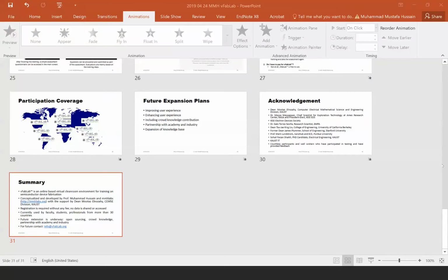So let's say that when we are done with the module level, then we will be providing the opportunity to have first a MOS capacitor, and then going from there a unipolar MOS field effect transistor. When we have them, we will be in a position to convert the MOS capacitor into an MIM, a metal insulator metal capacitor, which can be the backbone of a memory module, and the transistor as a logic module.